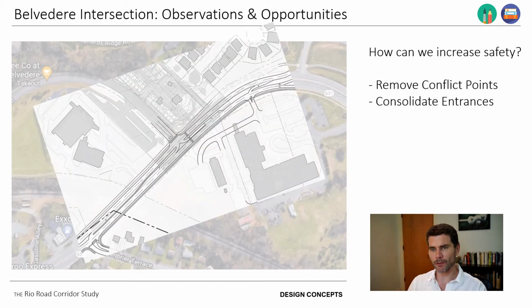So what are we proposing? Well, we're proposing what's called a green T intersection, and what this does is it minimizes the conflict points that a vehicle might have. And by conflict point, we mean really the point that an accident could happen. And so by introducing this green T intersection, we're allowing what could be a vehicle crossing maneuver to become a vehicle merging maneuver, which is a much safer maneuver for vehicles and should reduce a lot of the accidents that we're seeing at this intersection.